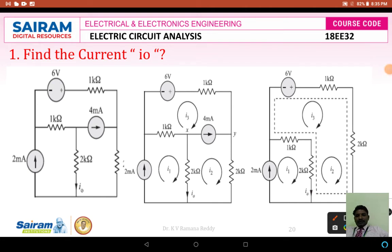And if you observe very closely here, for mesh 3 and mesh 2 there is a current source of 4 milliamperes. It is not possible to apply the mesh analysis, so we have to apply the super mesh analysis technique. I want to take the two meshes at a time, that is mesh 3 and mesh 2, as I am showing with the dotted line here. I want to apply the KVL in this way and write the equation.